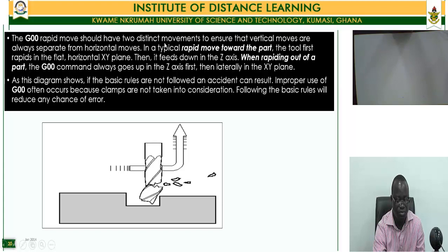That will be played very shortly, and that is showing you the G00 command. It's supposed to position the tool without cutting any material, which will be loading very shortly. Basically, as I explained, you move the tool into position without cutting any material.